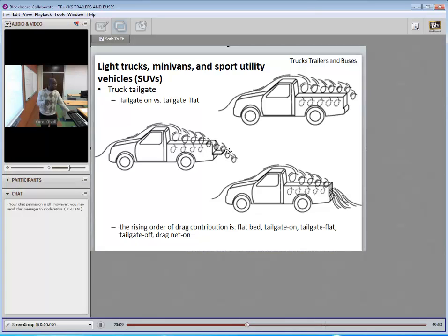And so the flow falls over and sheds off. Also note that in addition, now you have this extra length from here to here over which there has to be drag. So this incurs more drag than this.